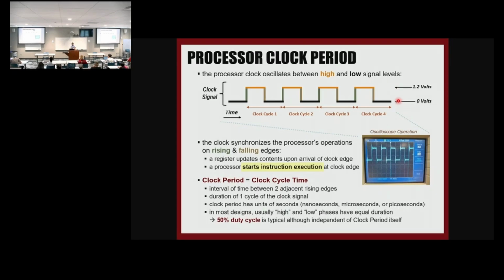So this is circuit level work. Usually in the circuit we have ground and we have VDD. VDD is a nominal voltage. And clock oscillates between VDD and ground. The VDD is the high state, ground is the lowest state. So for example, in this case we can have 1.2 volts as VDD, which is the highest state of the clock, and ground is always 0.